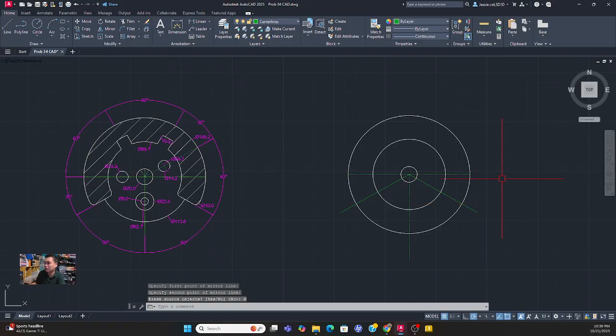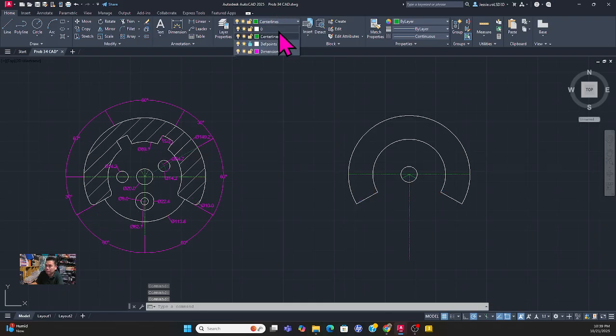Click this, hit enter, go to my center point, and then I'll mirror it, and I say no to erase. All right, so now that I have that, the next thing I'll do is trim out this little section here, as well as this. And you will see what I'm doing. Now I'm done. I'm going to click on this too, and I'll change it back to my construction segment. So now you can see it's turned white. All right.